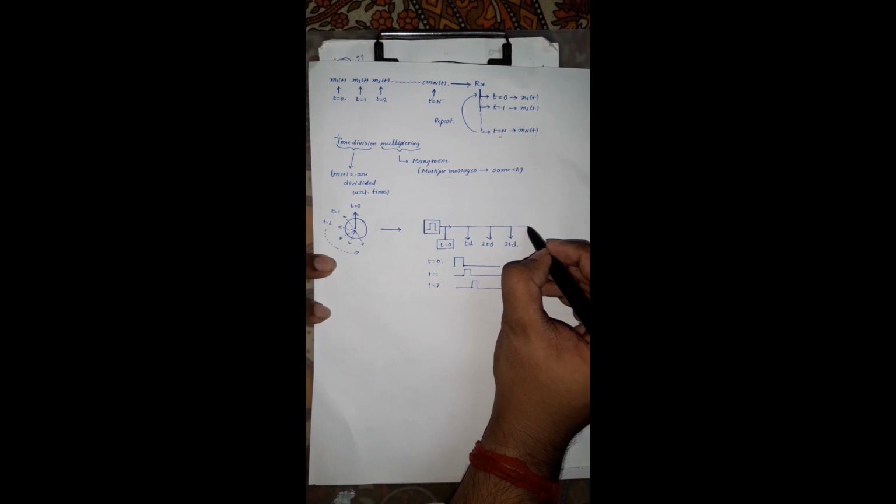What we are going to do inside this circuit is not so important, but for laboratory purposes, inside the trainer kit there is just a simple clock generator, that is the 555 timer IC. The timer IC is continuously generating multiple square wave frequencies. We are just delaying the frequencies for a certain amount of time delay.